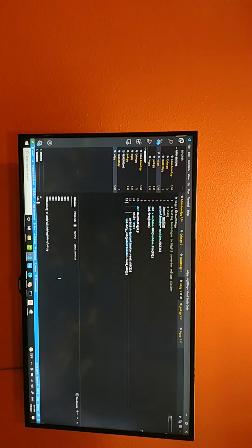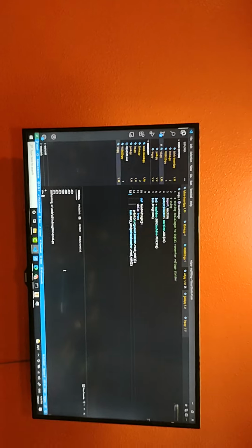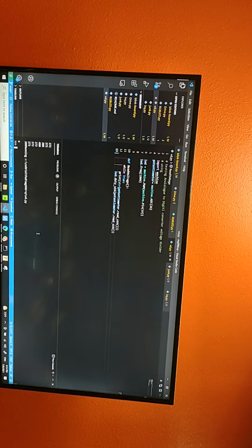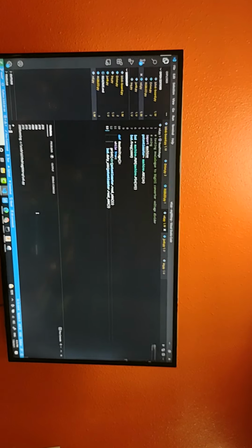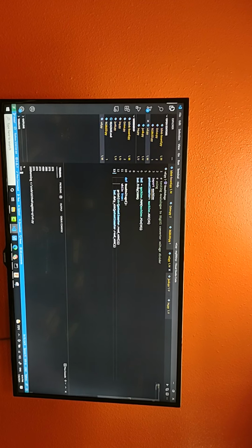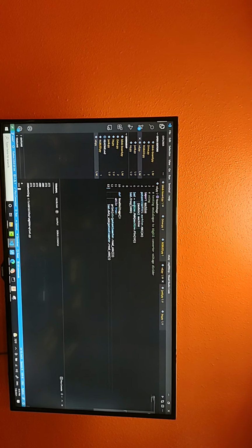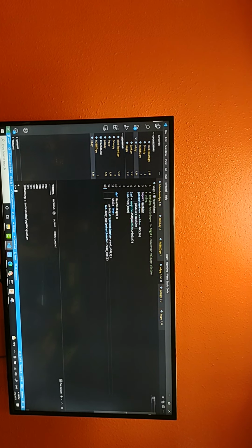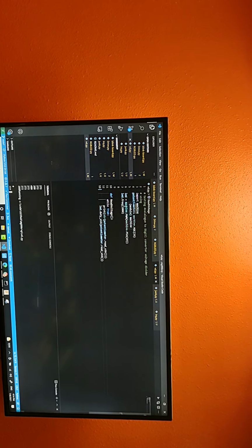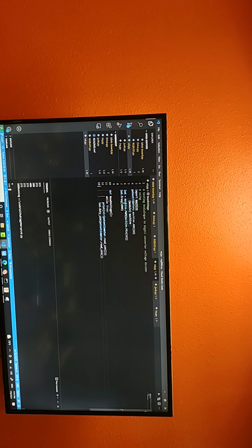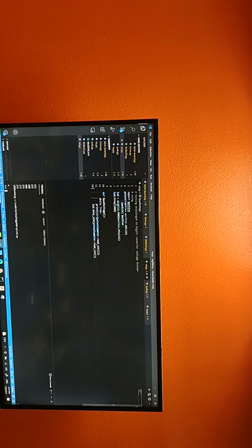Potentiometer, light emitting diode. Let me ask you, I'm sorry, I'm following your code now more intently. So the LED dot frequency 1000, that's the color code? Well, we're setting up a pin, pin 19, for PWM, and the frequency is how often it's changing back and forth. I bet if I changed it to 500, we wouldn't even notice any difference.